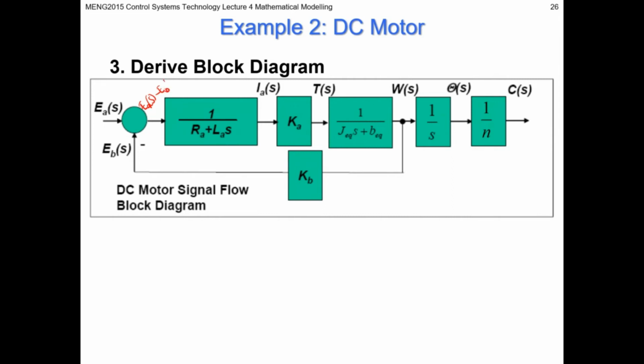So we have here that input EAS minus EBS. It's the difference, so what we're saying here is, okay, well, this looks like a feedback loop now because we know our EB is a function of something further, the speed of the motor. So that's like a negative feedback loop. We're applying a known input voltage, and the difference between this is what's going to accelerate our system.